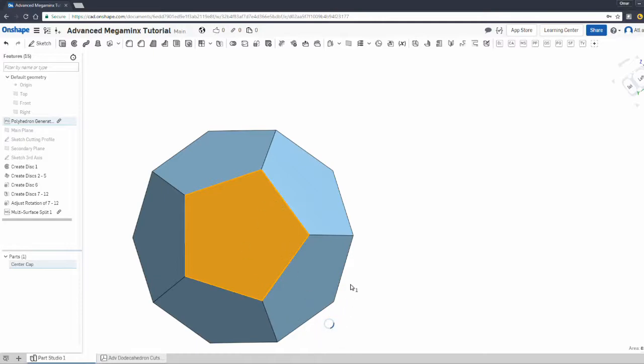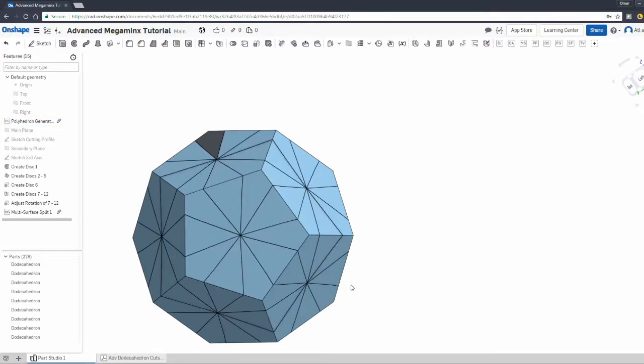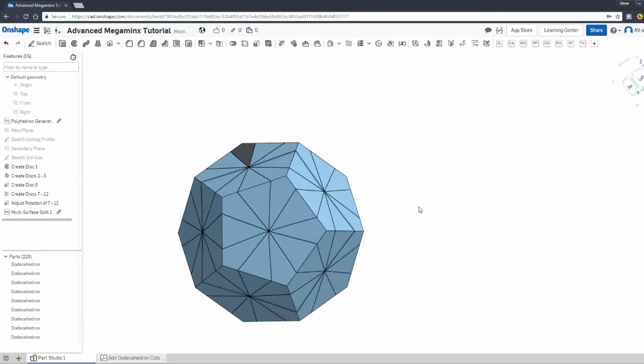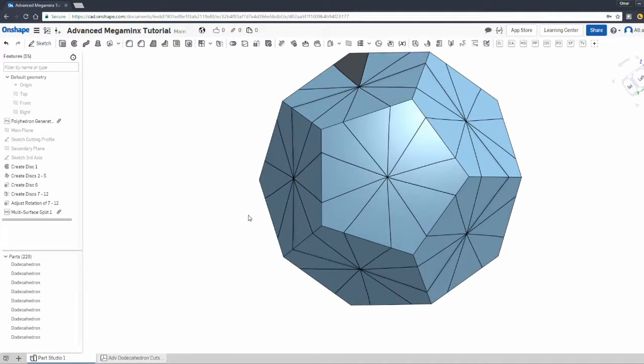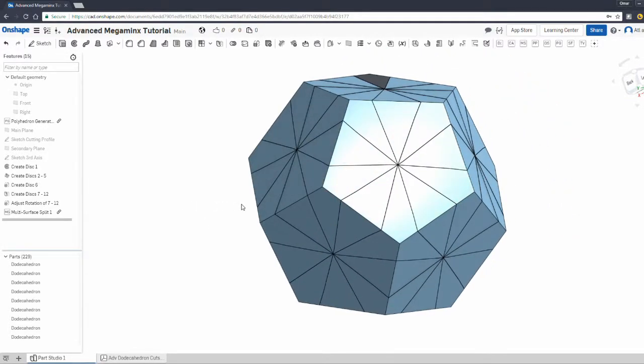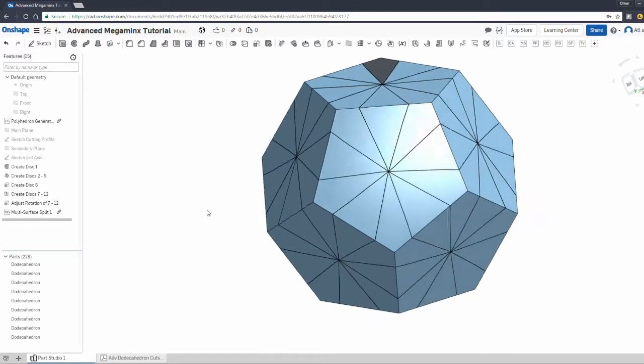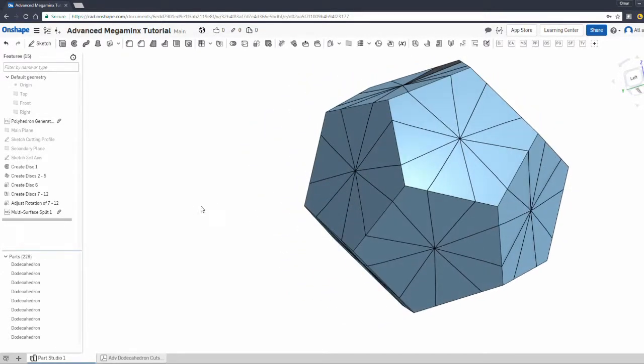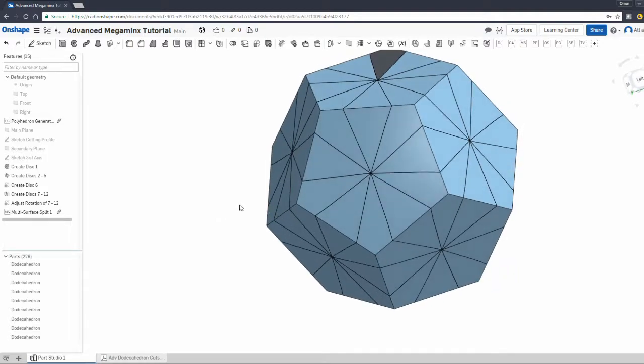It's spinning. But basically, when you look at this puzzle here, it looks exactly like a Pyraminx Crystal. And in fact, this is exactly how we'd model the cut of a Pyraminx Crystal. Now, that doesn't mean that the mechanism here is sound. It doesn't mean that you can 3D print this and say, hey, I have a Pyraminx Crystal. That's just the external cut, right? Now, if you print this, it's going to fall apart. The pieces won't be held together properly, and that's because the mechanism is not sound.